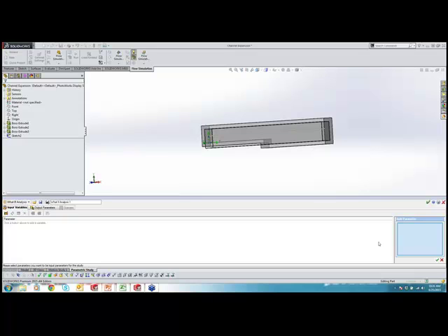Take a cut plot with the Excel data, take the averages, write that into a curve, and then write that as a transient boundary condition coming out of the hole. Okay. And so this is with that parameter. So say I think what I've got is a limit distance mate in there. Yep, that's exactly what you'd use.